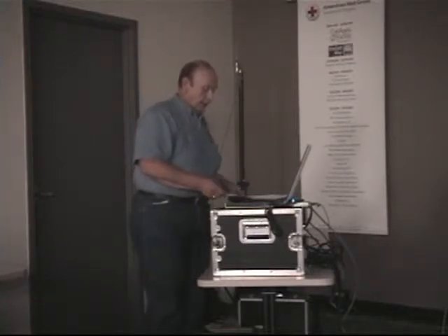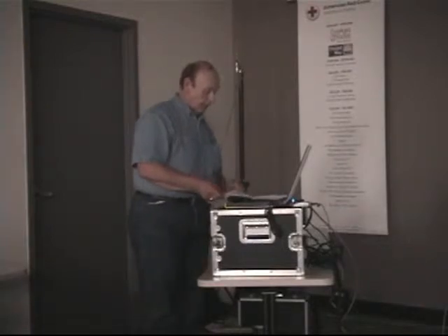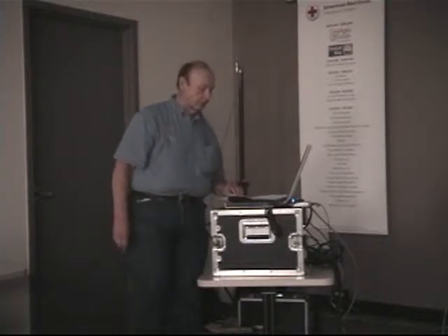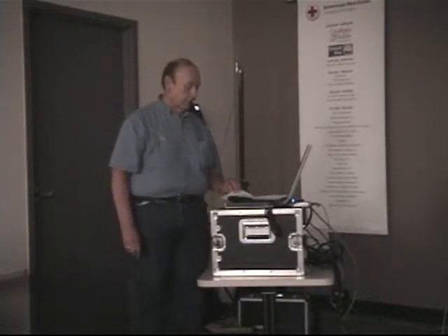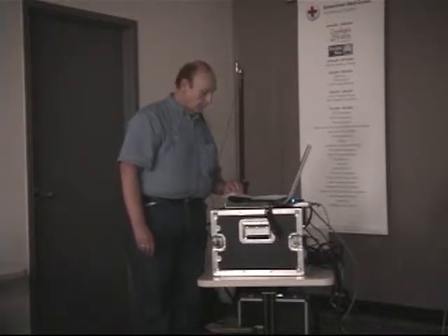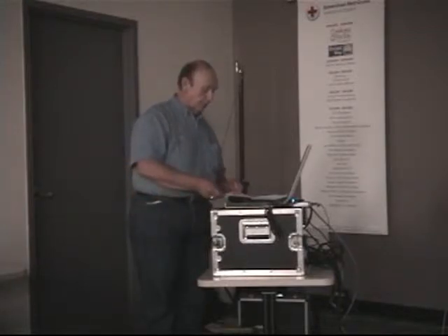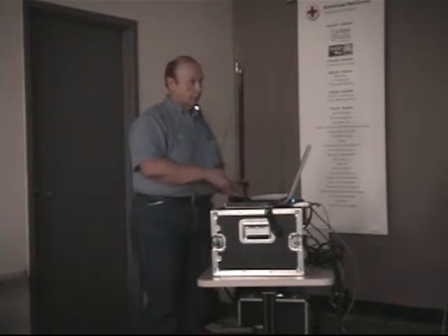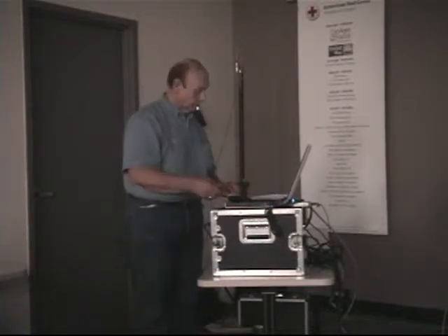The coders enabled receiving radios to detect and automatically correct transmission errors by analyzing bits inserted into messages that enable the receiving radio to tell if there's an error. The DMR standard specified over 14 different coders to be used. Each one's matched to the different type of traffic that is being transmitted. So that's why you get the forward error correction and why it's so good. Okay.